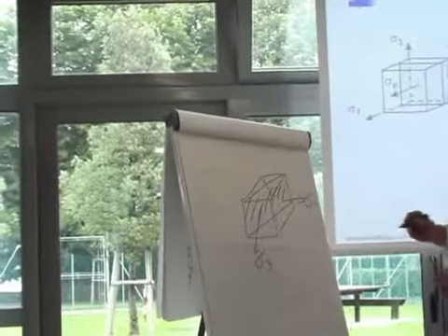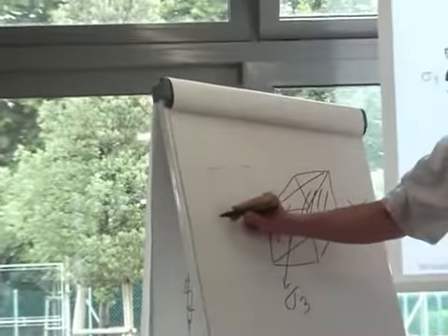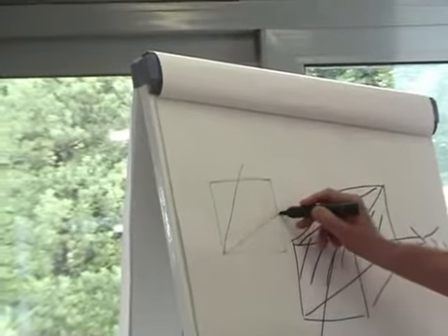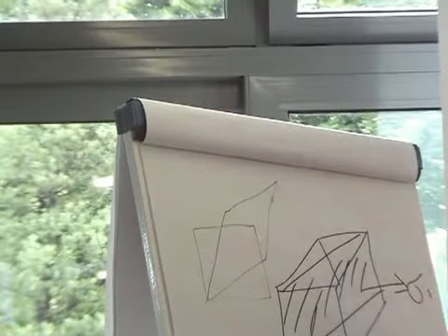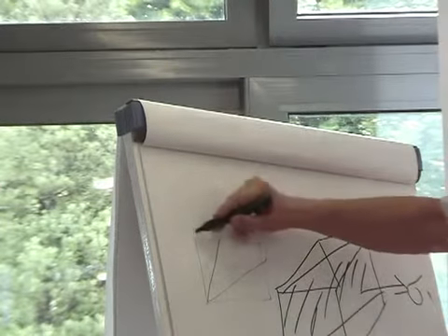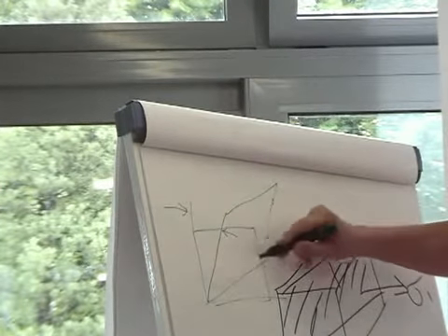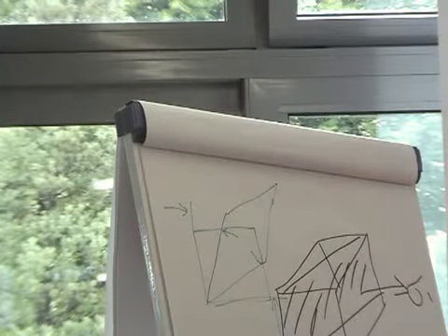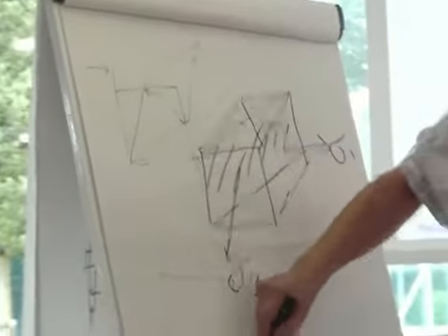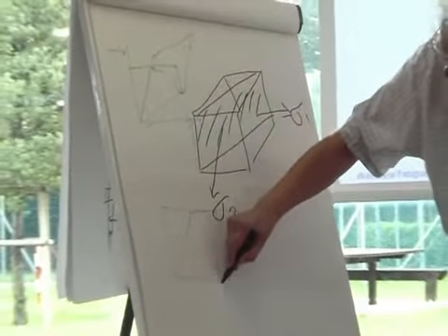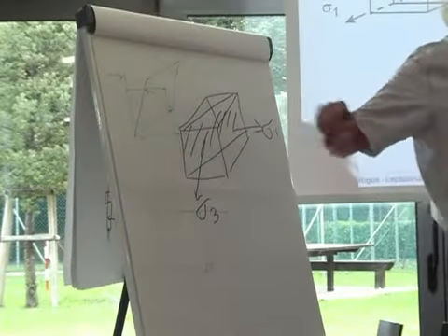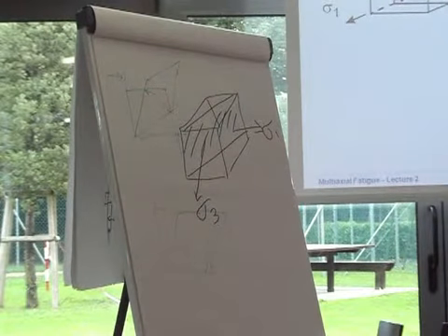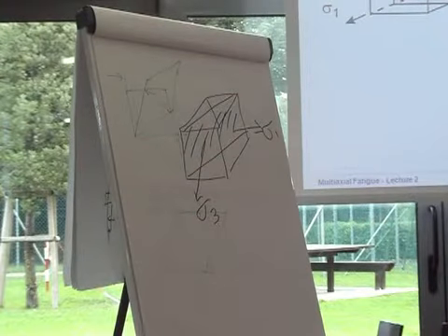So there's the original cube. And when you shear the cube in pure shear, it goes something like that. And there's shear strain on both sides. And to differentiate this case from this one, there's shear only on one side. So that's where the math comes from. And like you, I can't derive it all, but that's the concept behind it. In pure shear, you can shear on both sides like that. So anyways, that's always divided by 2, and that's how I remember it. I remember the funny little diagrams.